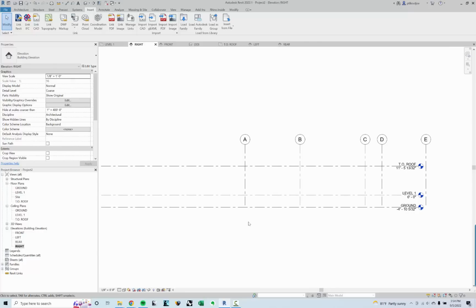As you get deeper and deeper into Revit, and as we get deeper and deeper into these tutorials, you're going to realize that the last thing we want to do is mess with the visibility of things because it's just going to make life very difficult. You want to be very, very diligent about your visibility. Now, if you want to turn things on and off to help with referencing and things like that, you can use that visibility graphic override, but you really want to avoid messing with templates if you can't see something or if you need to turn something on temporarily.